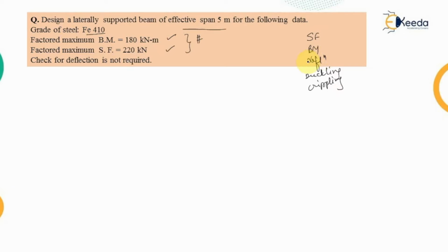and our beam should pass all the criteria. Now in the problem it has been said that the deflection is not required for the checking criteria because it is similar to the previous one, that is WL^4 upon 8EI, and it must be less than the value of L by 150. So the same procedure will be there, that's why we will not be requiring to check for the deflection. Everything else will be done here.